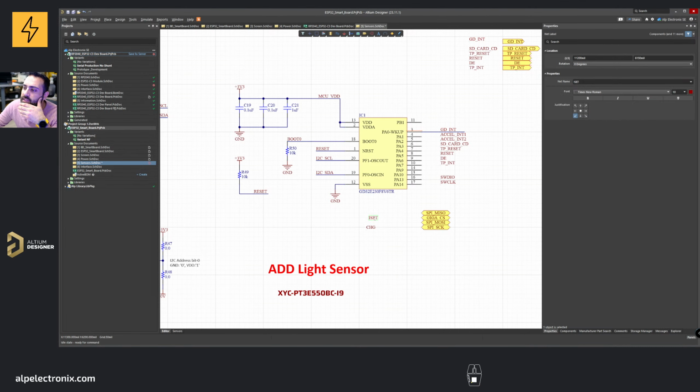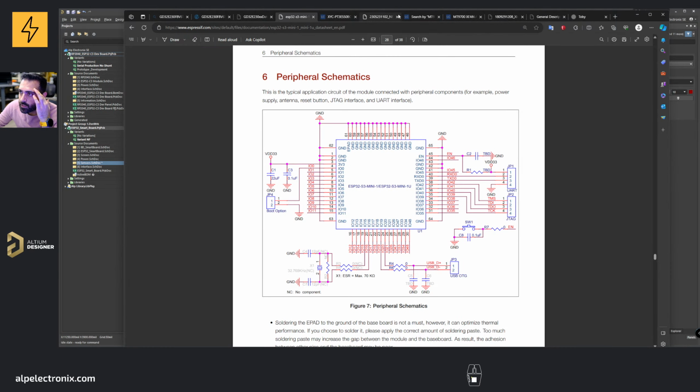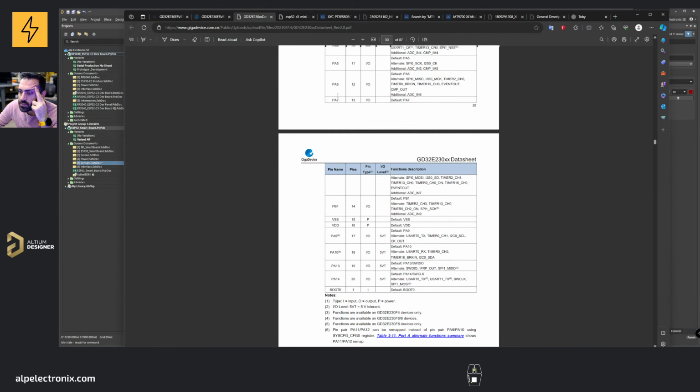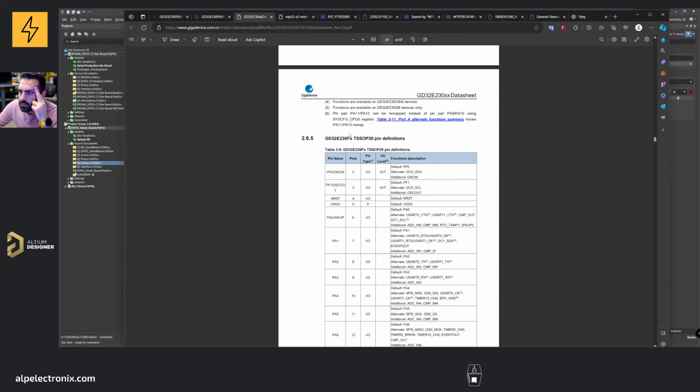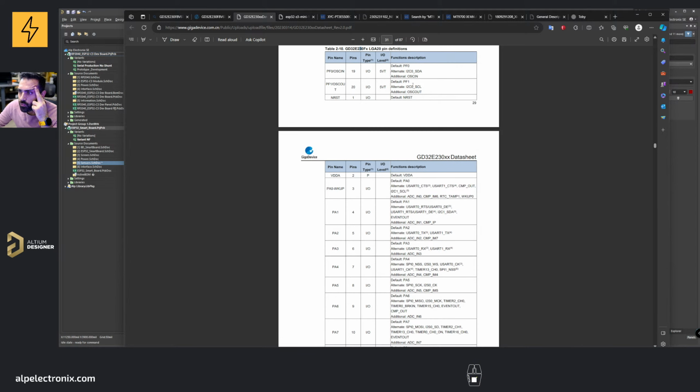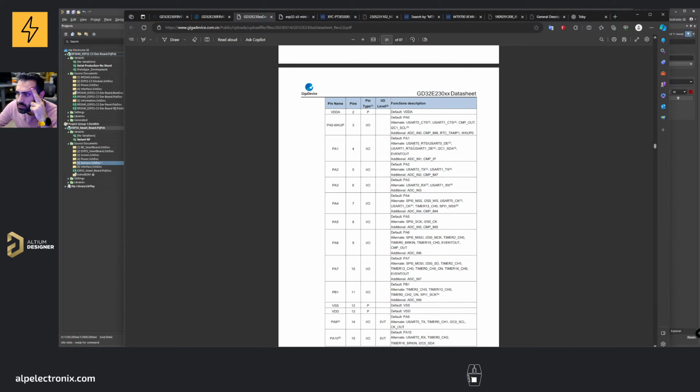I said the pin needs to be monitored with an ADC, but this charge is enough to monitor it with a digital IO, not an ADC. But let me open the datasheet. The datasheet is here. The footprint we use is LGA20, and the device is this one. Let's look for the ADC pins, like ADC in 0.